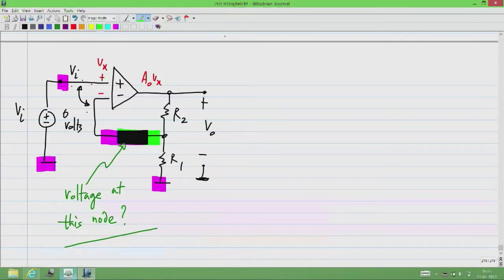So there is a question here, how is the gain infinite? Now that is the assumption we are using. Okay, we will design the op-amp to have a gain of infinity. Now in reality, of course, you will never be able to reach infinite. You will reach a very large number. So you can think of this infinity as an approximation to a gain that is very large. Okay, is that fine? So what is the voltage here at the highlighted node in terms of the input voltage Vi?